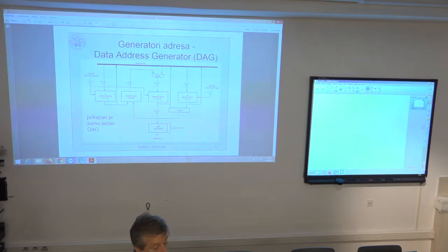And to perform this decimation, how do you access these data values from the fast Fourier transform buffer? You actually, after performing simple increment of the pointer, then you also bit reverse this address pointer. And now you get exactly the address you desire based on this decimation, either in frequency or in time.